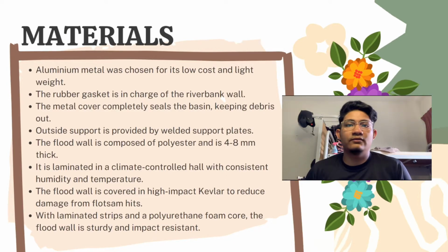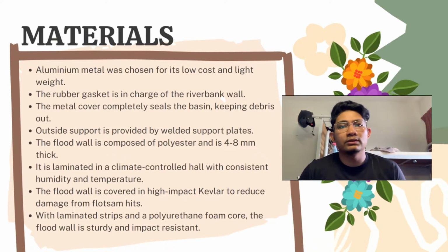The flood wall is covered in high-impact Kevlar to reduce damage from flotsam hits. With a laminate strip and a polyurethane foam core, the flood wall is sturdy and impact resistant.